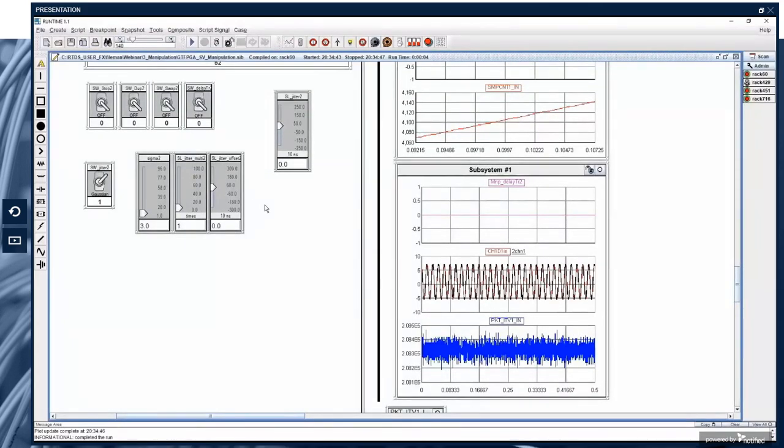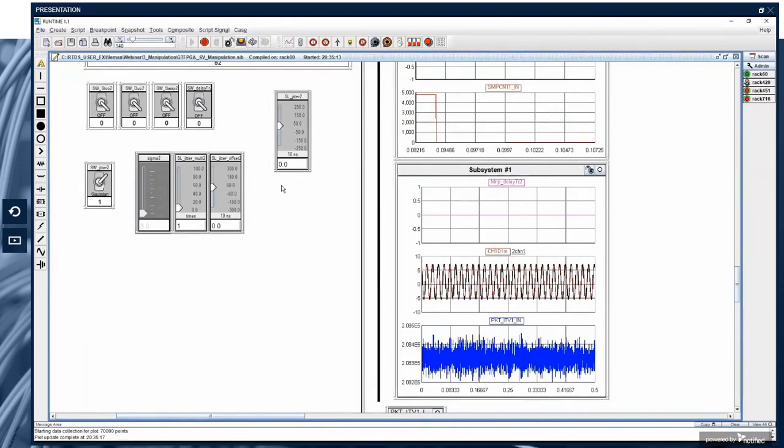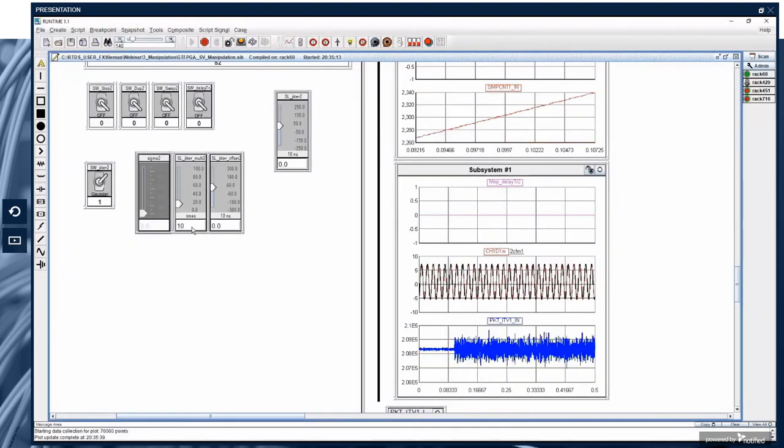We can rerun the case. Now we are applying Gaussian distributed jitter on the SV stream. Pay attention to the packet interval in the bottom corner. Now we will multiply the jitters to 10 times. The packet interval will be also 10 times worse. That concludes the manipulation part of this demonstration.